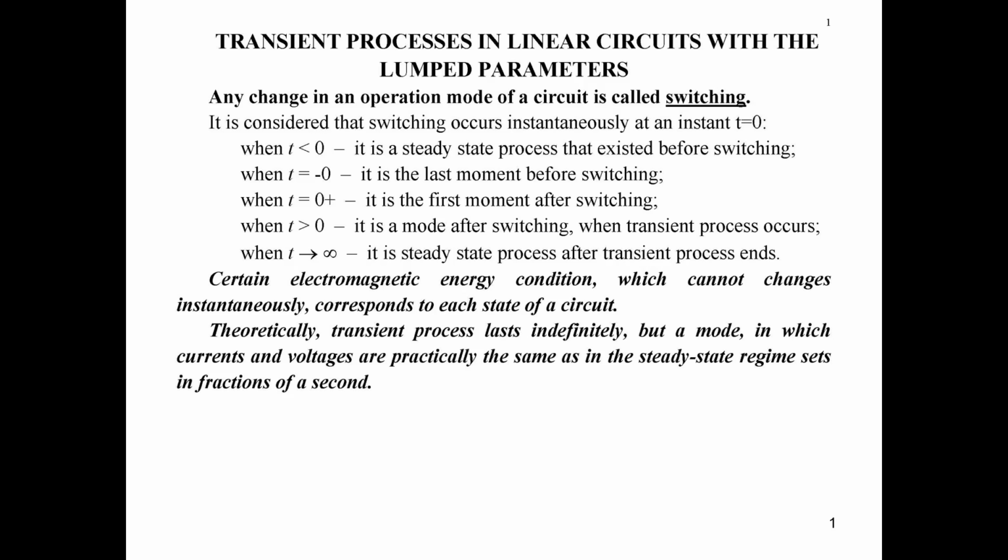So we may presume that in each point of the considered schematic, even if we consider, for instance, power transmission lines with rather big lengths of about many kilometers, all the same the length of the applied electromagnetic wave will be much more than the linear dimensions of this circuit.